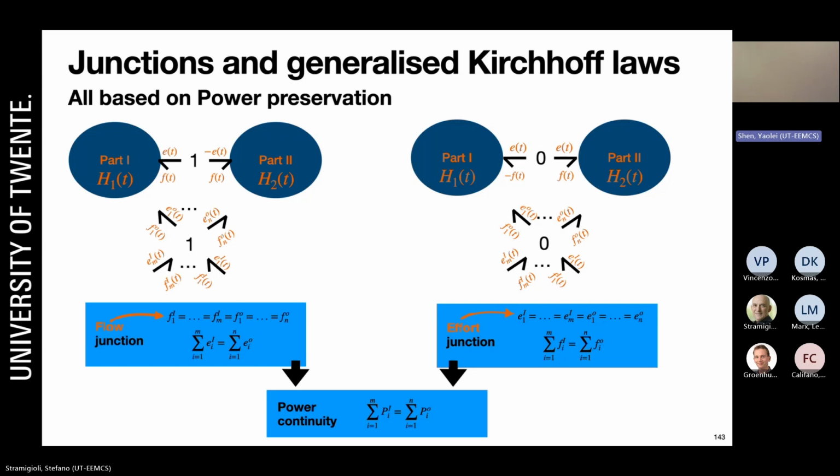So the way you do this modeling, in electrical circuits the things you use as reference are the potentials. So this has a certain voltage because it has a potential. A voltage turns out to be an effort, we will see. So I call this a zero junction. That is the potential of that wire. Here I have another potential of that wire, and I represent it with a zero junction. Here I have another potential. So these are the zero junctions; they represent the potential of that wire.